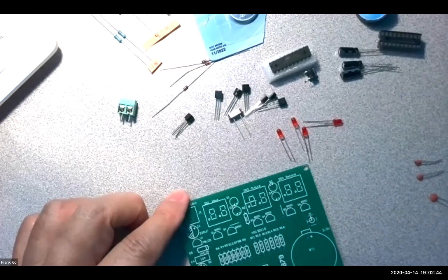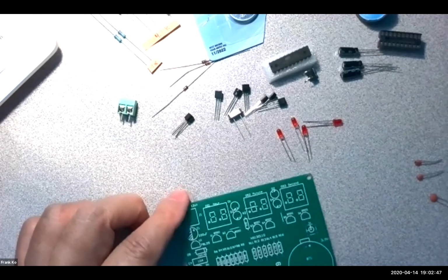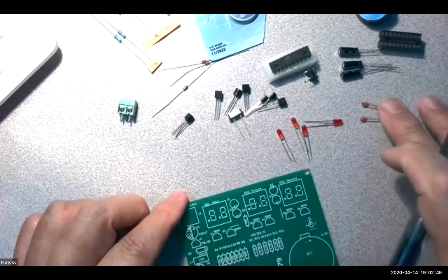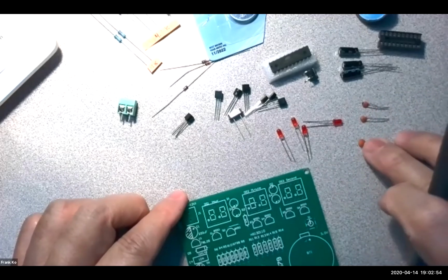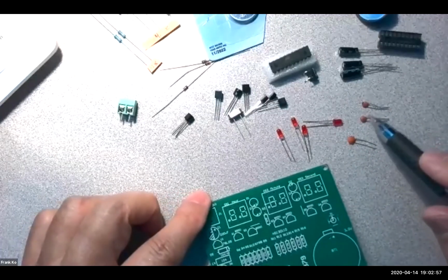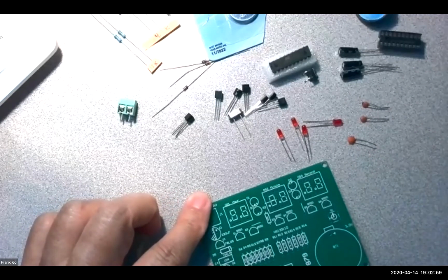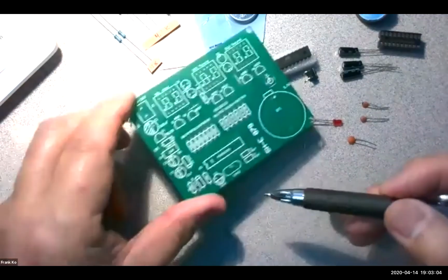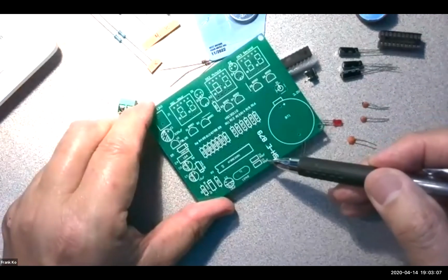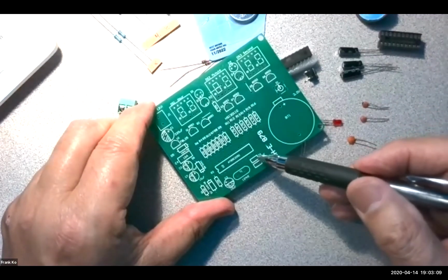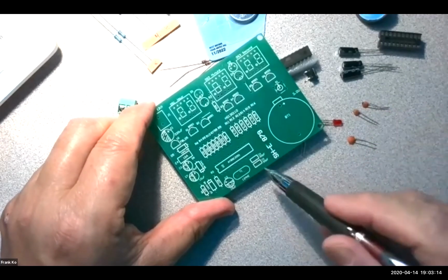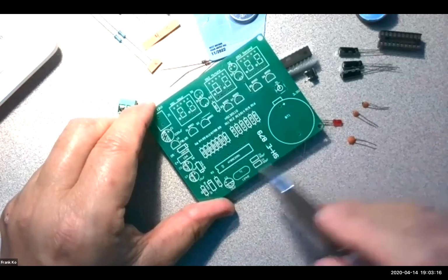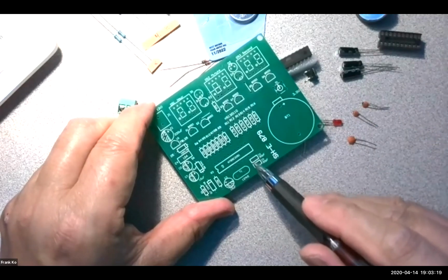Then you have ceramic capacitors. You have these little ceramic capacitors, and then you have another ceramic capacitor over here that's a little different in size. The 2 little guys are marked with a 30, and they are going to go on your board as 30 picofarads, 30 picofarads here and 30 picofarads here. They are non-polarized. It doesn't matter which wire of the capacitor goes into which hole, but you have a pair of those capacitors going here and here, okay?